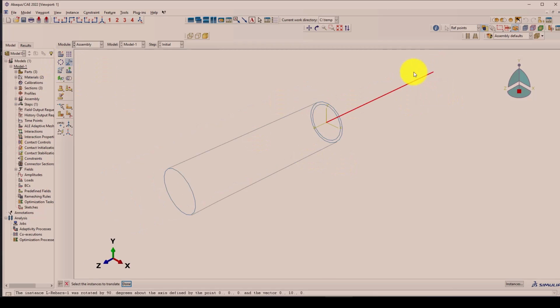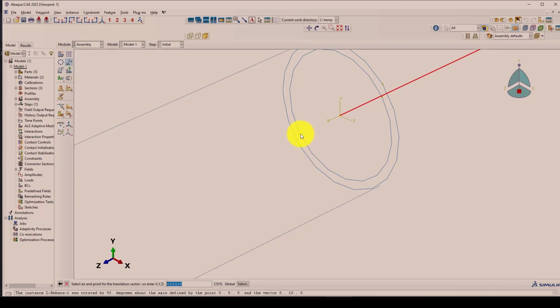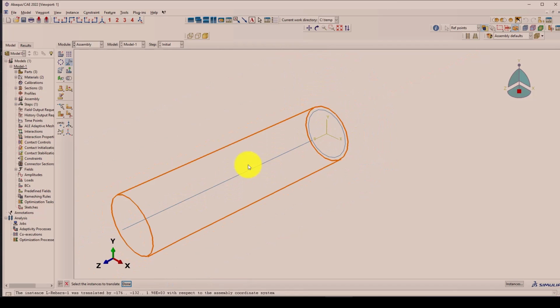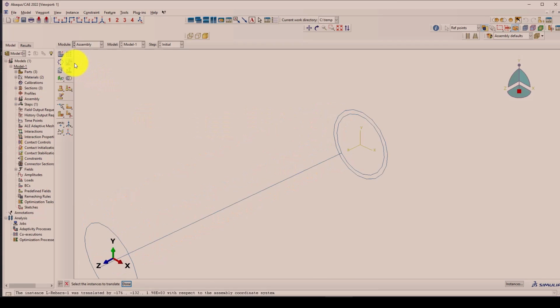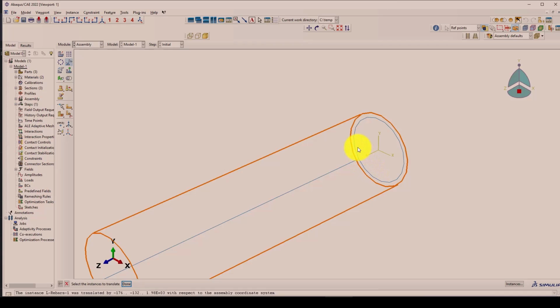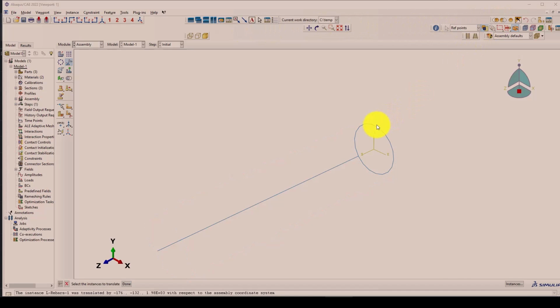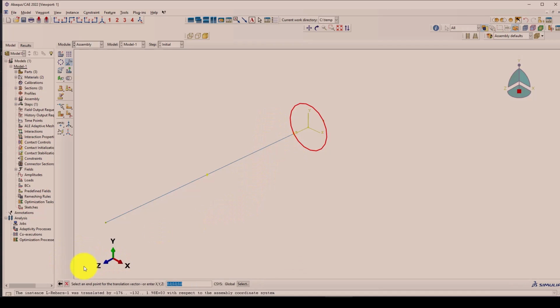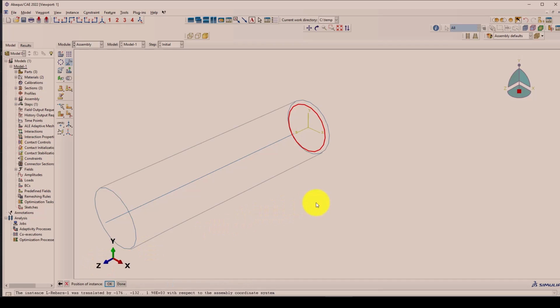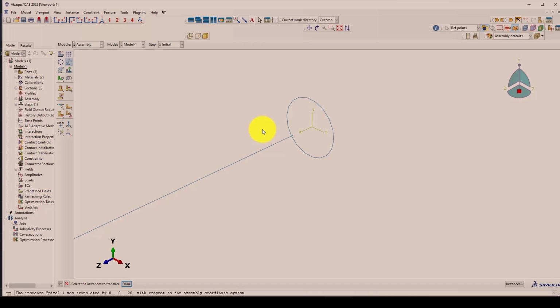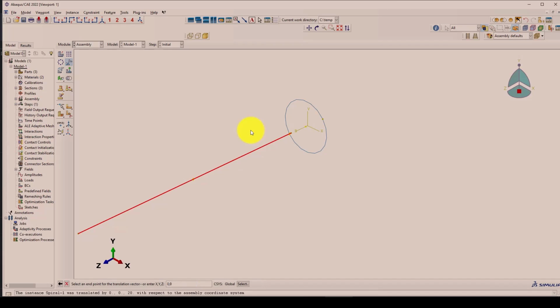Now I'm going to shift or move it to this point. Now both elements are in the same place, but I want to move using this command. I can select this one, go to this command, move, and take the point 0 0 and push it in Z by positive 20. That's it. Next I want to select this one, take 0 0 and push it by 0 0 10.